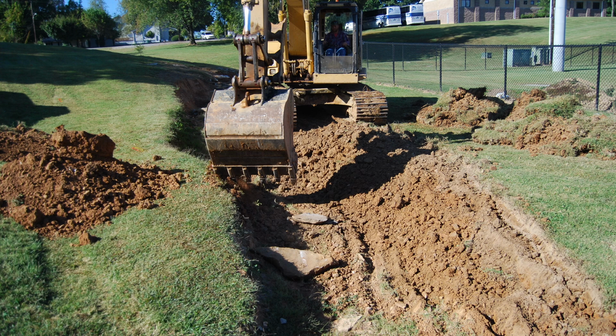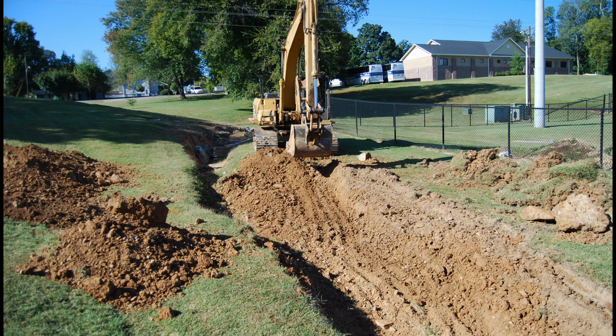This was not easy because the steel bucket would catch on the large boulders and shake the machine and the operator. We removed as much soil as possible that was on top of the rock. Had we left a layer of soil over the rock, it would have eroded. Due to the uneven surface of the bedrock, it was not possible to scrape the floodplain clean like a tennis court.